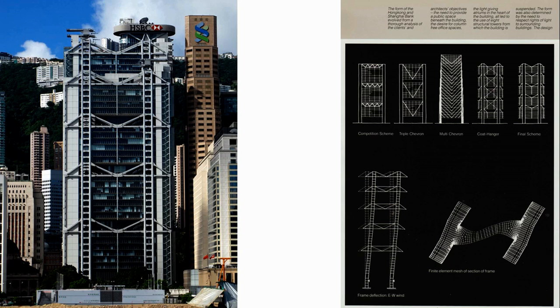So again, here we have, you can see there's a ladder truss here. It's actually a Vierendeel truss, you can see by the connections, isn't it? There's a number of these on plan, and what's happening every so often there is it's almost like a coat hanger, isn't it? It's a big coat hanger, a larger truss that connects these two.